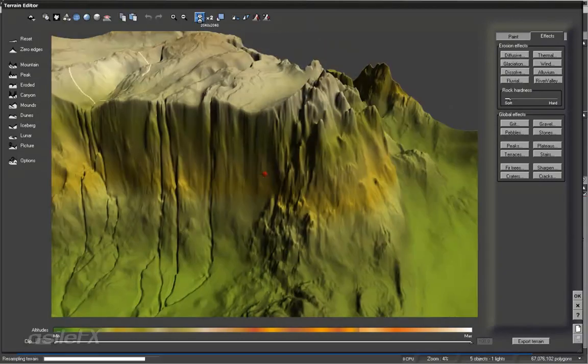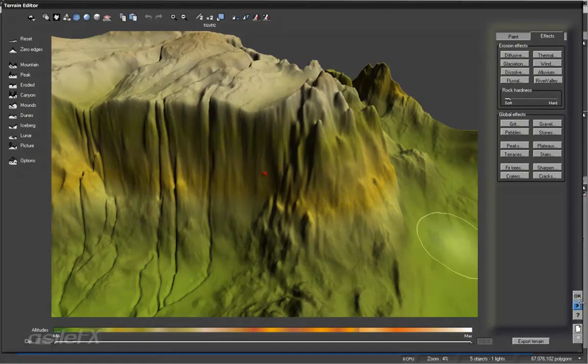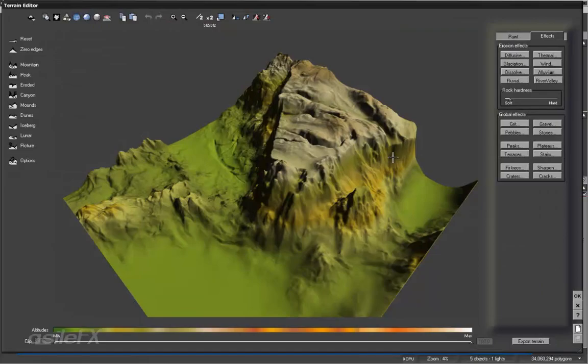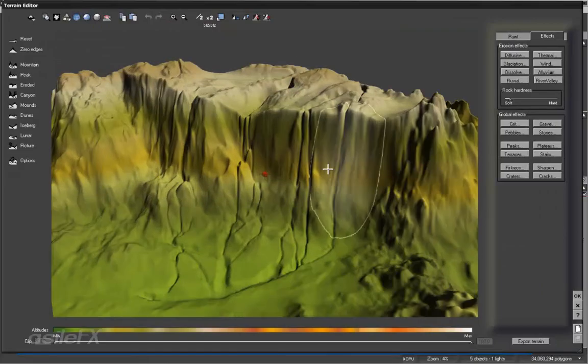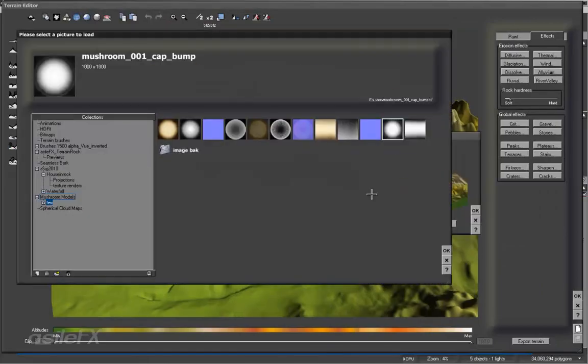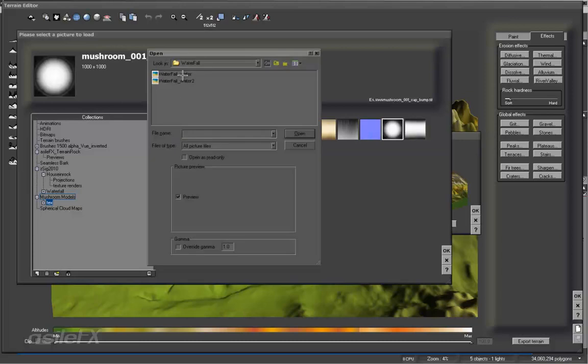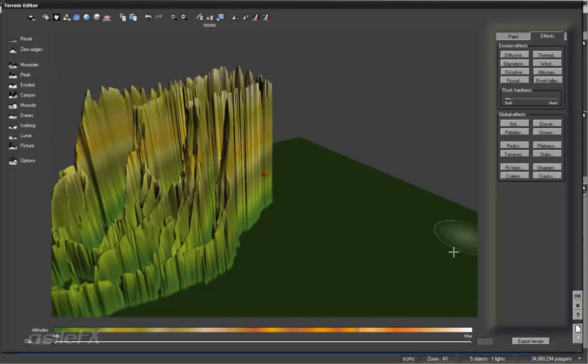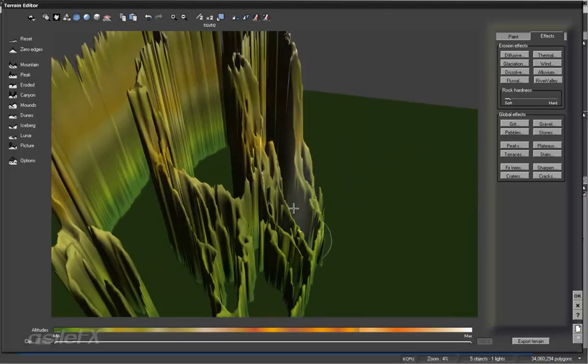So then, going back, downsampling the terrain, I also went and clicked OK afterwards to apply that, then went back and edited the object in the terrain editor, went to Picture, and loaded in that image. Setting it to subtract, 30%, hitting Enter after typing in 30, previewing, and clicking OK. So that did work successfully.